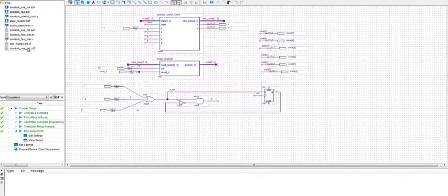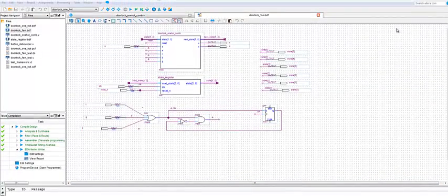Okay, and once you've created your .v file for your combinational logic, just go ahead and make a symbol, as I've done here. I have my Doorlock One Hot combinational symbol. It has inputs for the states that are 6 bits wide and outputs for the next state that are 6 bits wide. It has all of the inputs for each of the colors, R, G, and B, as well as A being that input to say that a button got pressed.